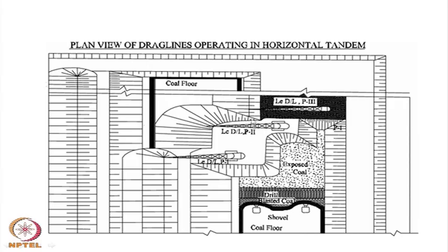This is the spoil dump. Here some of the key cut material has been dumped. Now you are going on excavating in this direction, the overburden. So, this spoil and that key cut, next key cut will be given, the material will be coming over here, this platform will be going in these directions.